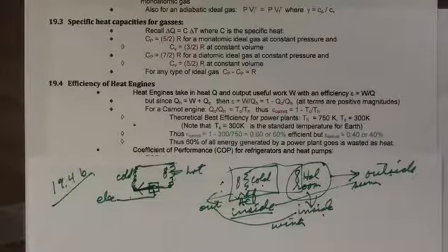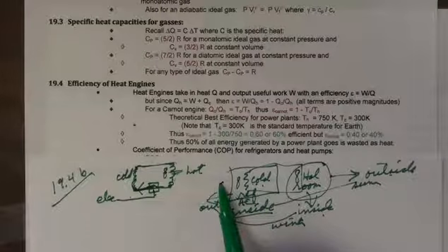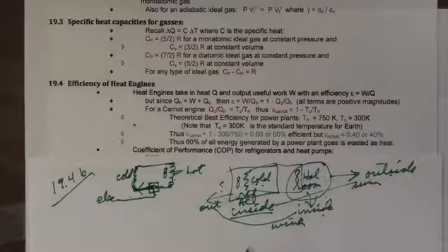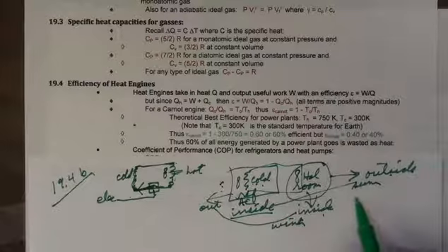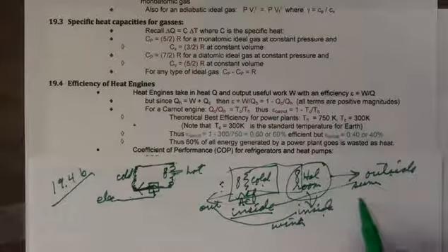You can say, well, is this process really working? Well, actually it is, because these cold coils will pick up some heat, even in the winter, from the outside. Although the colder it gets out here, the less efficient this system is. It turns out that in a state like South Carolina, this system is more efficient by about a factor of 2.